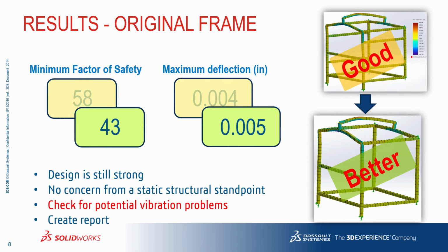But when I'm really after granular results or stress results at the junctions, that's when I really want to get into shell results. So beam is fantastic because in 30 seconds I can make a design decision about what wall thickness weldment do I need. In this case, go from 5/16 to 3/16, cut the price in half. Awesome.